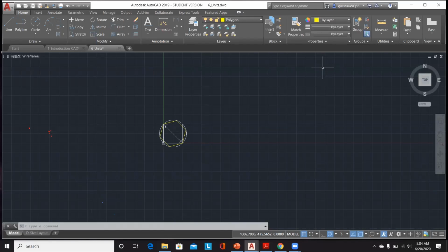And then I changed the system of units to millimeter, and when I measured it, I got the dimensions to the exact millimeter. So by default, my drawing space was in, let's say, fractional inches. And then I used scale factor to increase my drawings to millimeters.